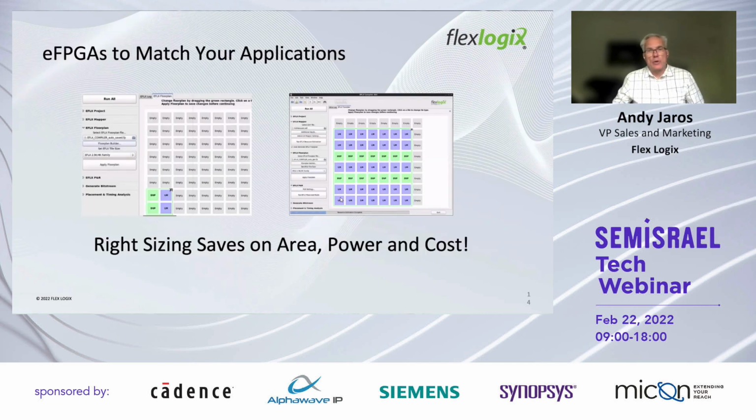The other advantage of integrating the FPGA is the ability to actually choose the size of FPGA fabric that you want. FPGAs often come with features and interfaces that already exist in the ASIC, like we talked about with SerDes in the last slide, but those circuits tend to be on the ASIC as well. Embedded FPGA allows you to add in just the FPGA fabric and how much of that fabric you want. What we're showing here is our graphical user interface that allows you to scale and size the embedded FPGA, the amount of FPGA fabric that you might need for any given market application.